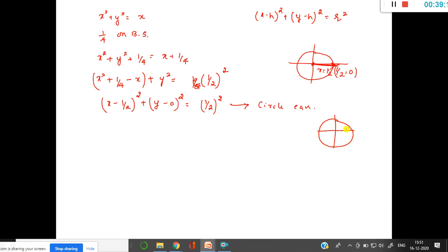which is supposed to be mapped within the unit circle, within the unit circle in the z plane. So more than a unit circle, it is representing with radius of half. So this is the entire frequency of S plane. Entire frequency of S plane is mapped well within the radius of 1 by 2 within the Z plane. So obviously the system is stable. System is stable, no doubt at all, right?